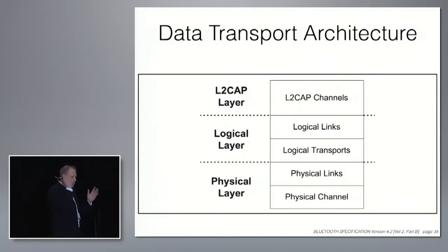So it was a little bit of a struggle trying to get the concept around. When I see physical channel, I'm thinking of channel 6 or channel 1 or channel 11. With this, though, because it's frequency hopping, it's not a specific frequency space. It's a function, or almost like a service, that the Bluetooth is providing. Once I understood that, it all made sense. So I've got a physical channel which has its own hopping and frequency pattern to it.